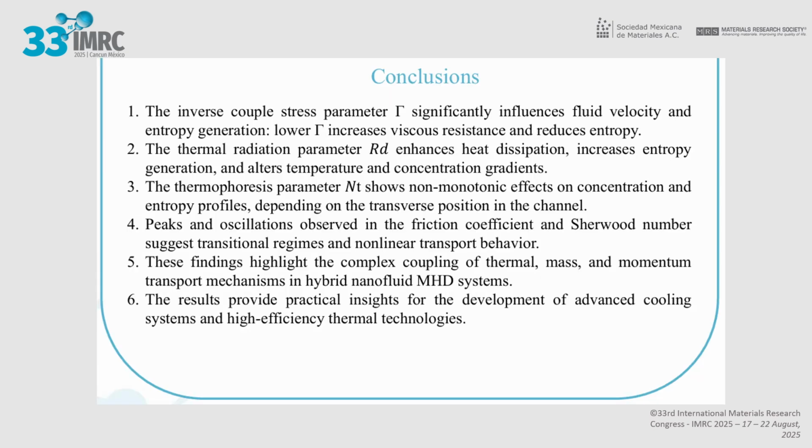Conclusions. 1. The inverse coupled stress parameter gamma significantly influences fluid velocity and entropy generation. Lower gamma increases viscous resistance and reduces entropy. 2. The thermal radiation parameter Rd enhances heat dissipation, increases entropy generation, and alters temperature and concentration gradients. 3.